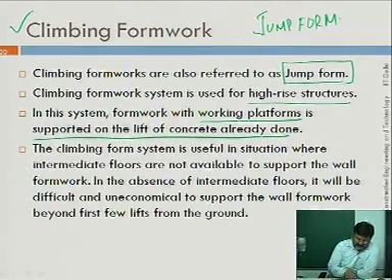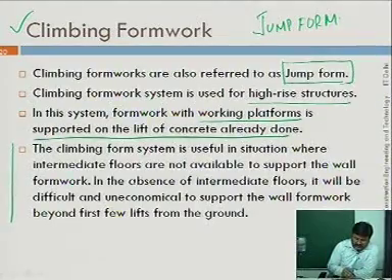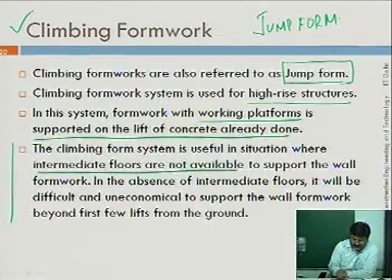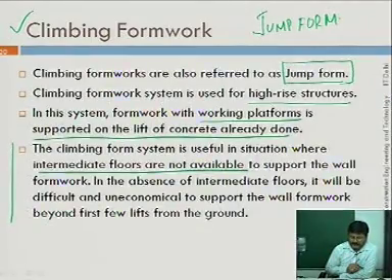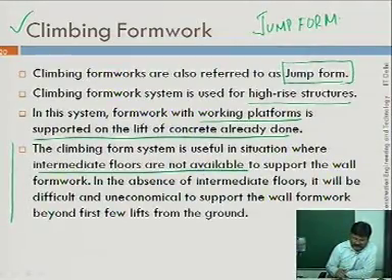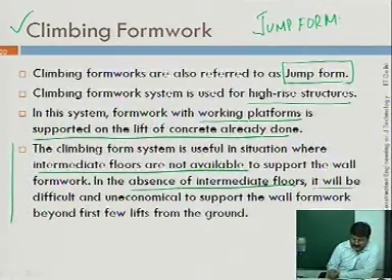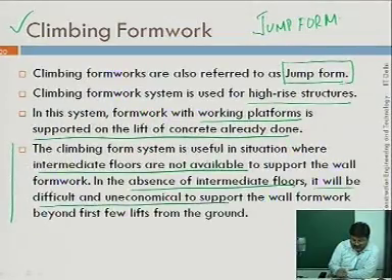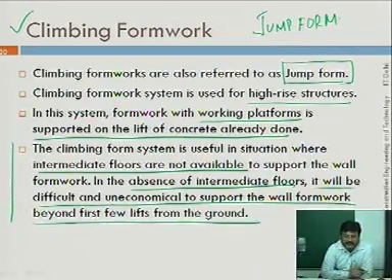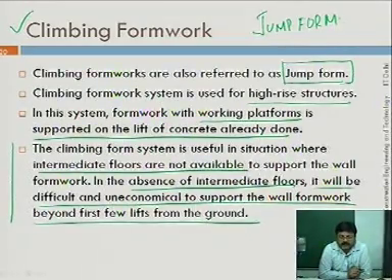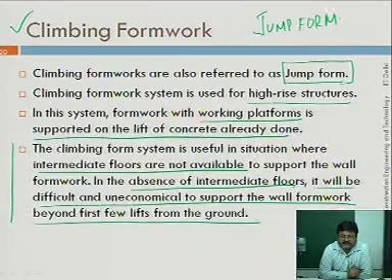Now these systems are useful where you don't have intermediate floors. In the absence of intermediate floors, you will find that it will be difficult and uneconomical to support the wall formwork beyond the first few lifts. I will show you with the help of one sketch.